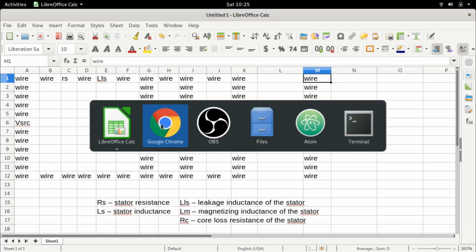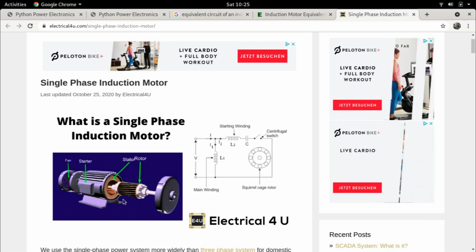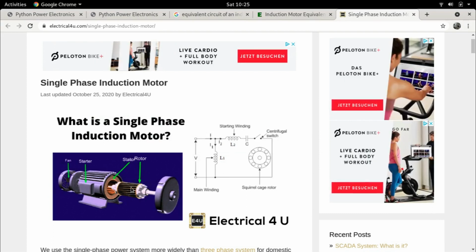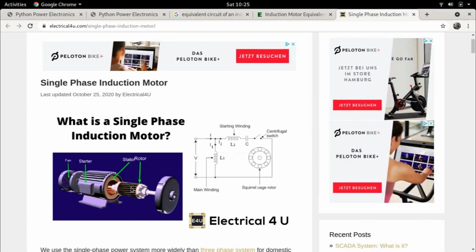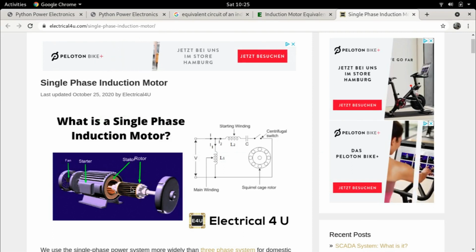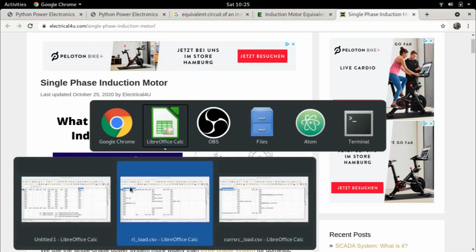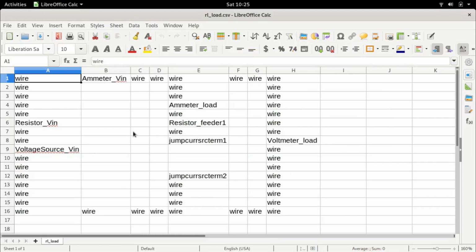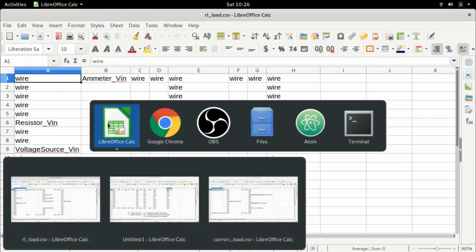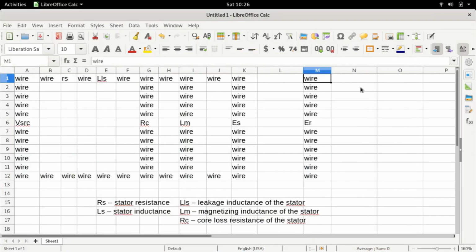Now you could say that there is nothing in the rotor circuit, it's just short circuited bars. But remember, any bar, any wire will have an inductance. So there will be a resistance, there will be an inductance. So we have to model that as well. So what that means is we are going to repeat part of the circuit.